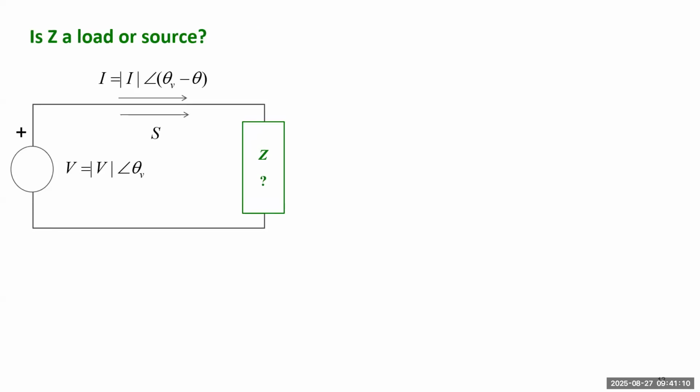So next, let's go back to this simple circuit. Now we have gotten rid of all the sinusoidal waveforms. We just use all phasors, all complex numbers, to model the circuit. So we have the current phasor, the voltage phasor, and we also have the load impedance. And we define polarity like this. We draw this equipment as a circle. We just assume this is a source, but you actually can define anything to be a source, because in an AC circuit, any branch of the circuit can consume energy or generate energy temporarily. We don't worry about their actual role.